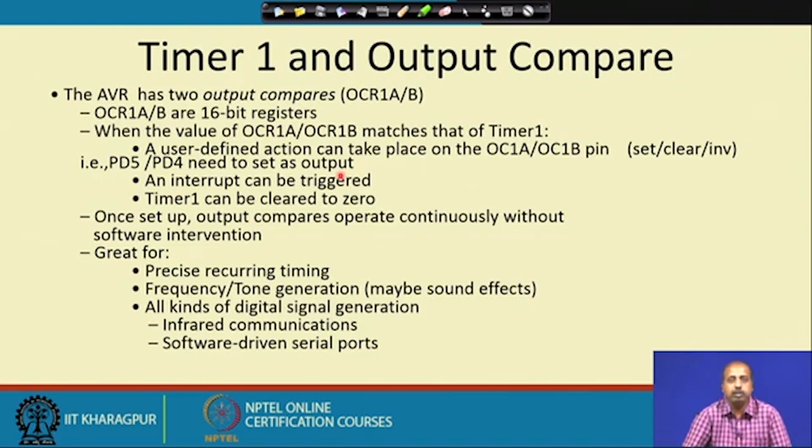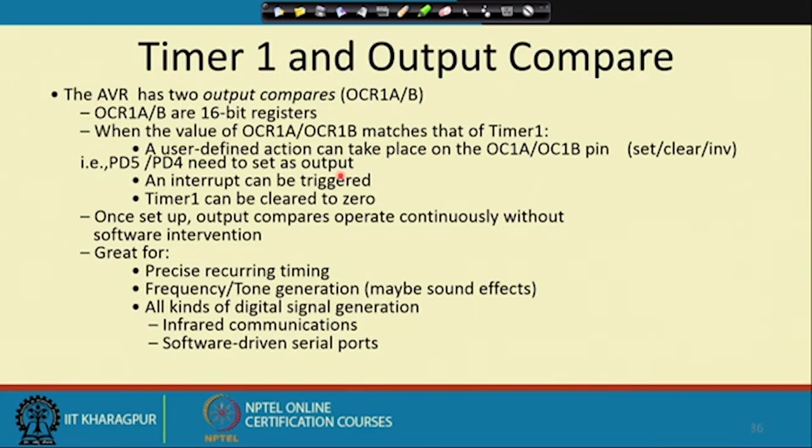In other processors, for example in the 8051, if a timer starts and then overflows, it gives an interrupt. But for in-between time values, if you want to get some notification, that is not going to happen. You have to stop the timer at that time value, and only then can you get that notification.